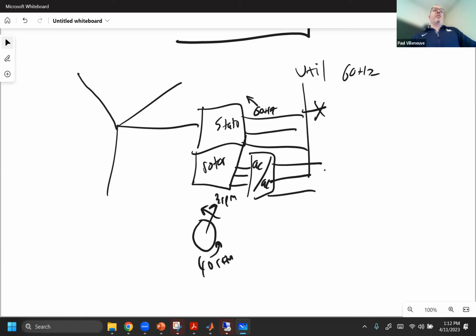So these wind turbine, these doubly fed induction generators are terrible for supporting the grid under fault conditions because they exacerbate the fault. When a fault occurs, all the voltages on the system are changing and are dropping. You're feeding a lot of current to one location, so the system voltage starts to collapse. Well, now you have wind turbines that basically shut off because they have no magnetic field. So they exacerbate the fault.